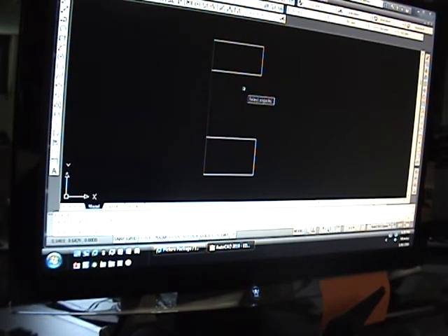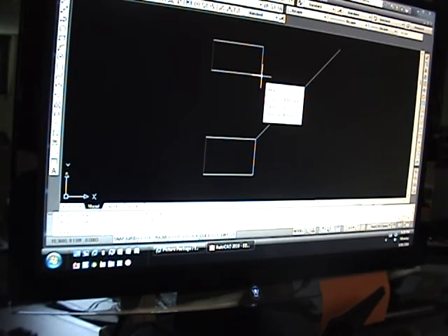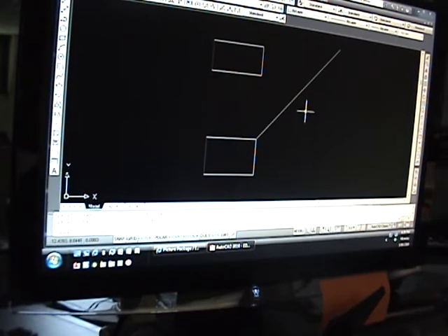Now you can get rid of your projection lines. Now we're going to look at going ahead and projecting over the box for the right side view. Now how do we do that? We're actually going to take a line from here, and we're going to take it at a 45-degree angle. Because if you project from the top to the 45-degree angle and back down, then you have a 90-degree projection. So let's grab one of them and bring it down to here.